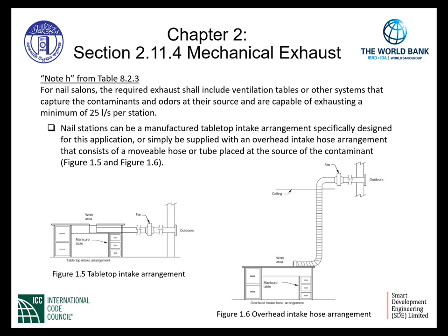Nail stations can be manufactured with a tabletop intake arrangement specifically designed for this application, or simply be supplied with an overhead intake hose or duct arrangement that consists of a movable hose, duct, or tube placed at the source of the contaminant. Figure 1.5 and Figure 1.6 illustrate both of these applications.